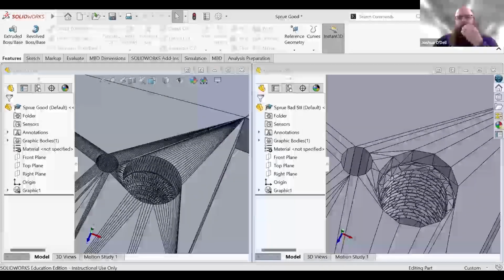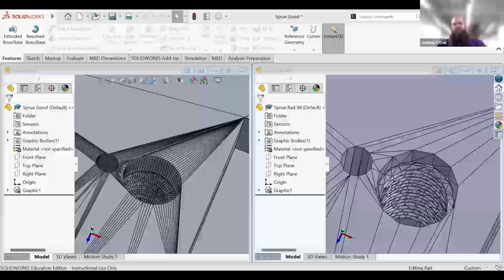Are there any dimensional differences when using certain printers and materials? So the dimensional differences can change, especially since you're heating up the filament, it's expanding during that time, right? So as it starts to cool, it's going to begin shrinking again. A lot of materials already have that scale factor baked into them. For all of our printers, we include some sort of shrink factor, and it's usually almost entirely material specific. So we'll print a 1-inch cube and measure it afterwards to see how much we're shrinking based on the material, and then add a scaling factor to that.